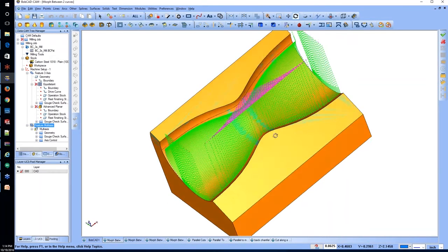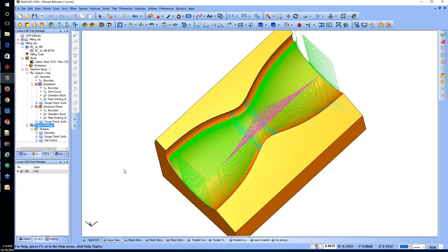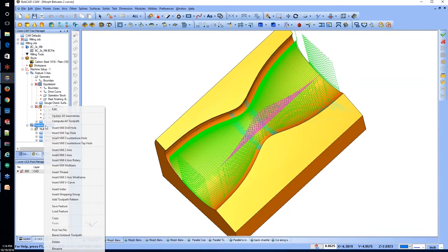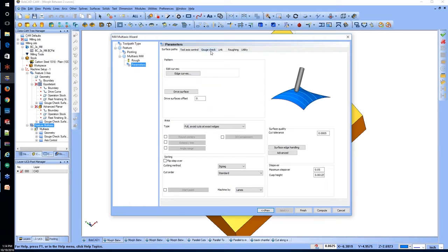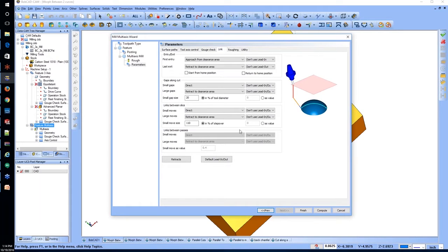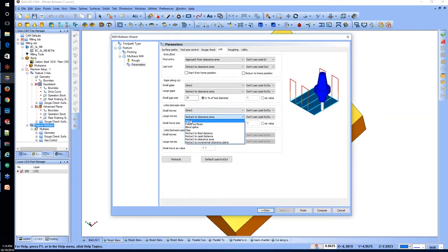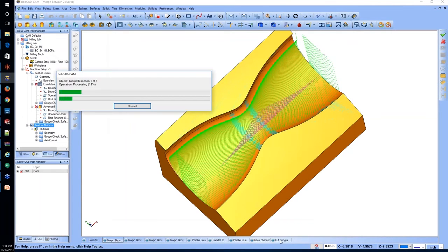These are just because the tool is coming this way, and it doesn't continue on along it. Okay. So what you're able to actually do with those, okay, these would be considered retracts. You can go into that actual option. So on a normal toolpath, if that's what you got, that's what you got. There was nothing you could do about it. These toolpaths, you can go in and eliminate a lot of those. So you go down in here into the linkage side, and you say, cool, let's go ahead and set links between slice. We don't want to retract. We just want to do a direct. What that does is that alters those options to just basically go straight to the next one and continue on.